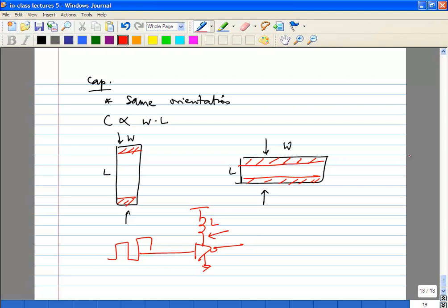I assume you have seen this before in other courses, right? So if you look at the voltage here, you're going to see much worse than this. You're probably going to see something like this. It can drop very low depending on the current you're drawing. It won't be VDD anymore. For the project, we're just assuming ideal VDDs. But in the real case, remember that from the circuit, you're routing a long way to the pad. You have a bond wire which goes off chip. You're going to route on the PCB and go somewhere else.